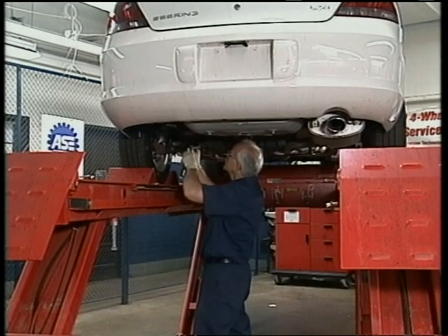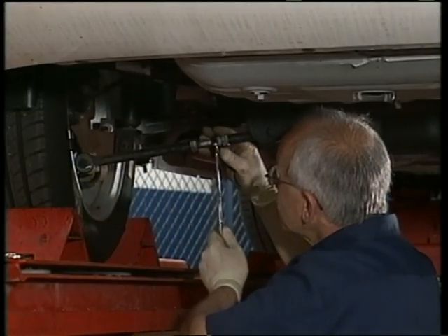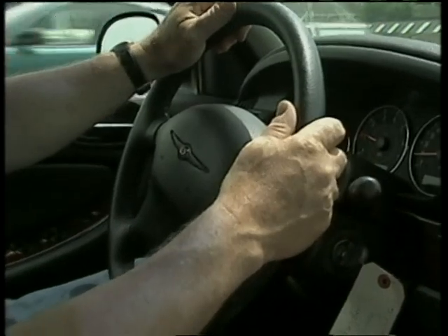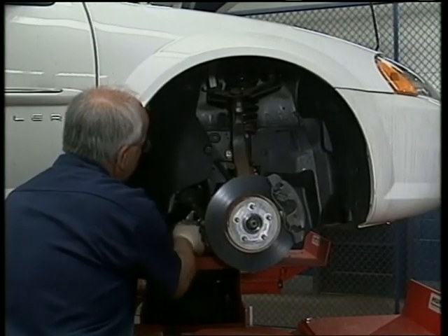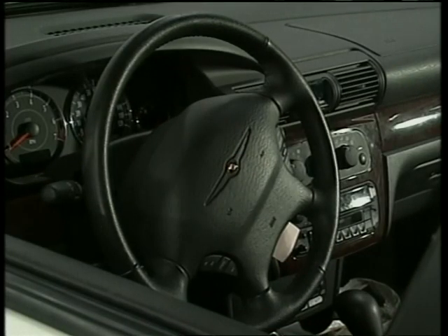To adjust thrust, begin by setting the rear toe equal in reference to the center line. Once the rear toes are aligned with the center line, set the individual fronts in reference to the thrust angle. This assures that the steering wheel will be straight ahead for straight ahead travel. If you set the front toe to the center line but ignore the rear toe angle, a cocked steering wheel may result. It's a steering wheel that's not straight.